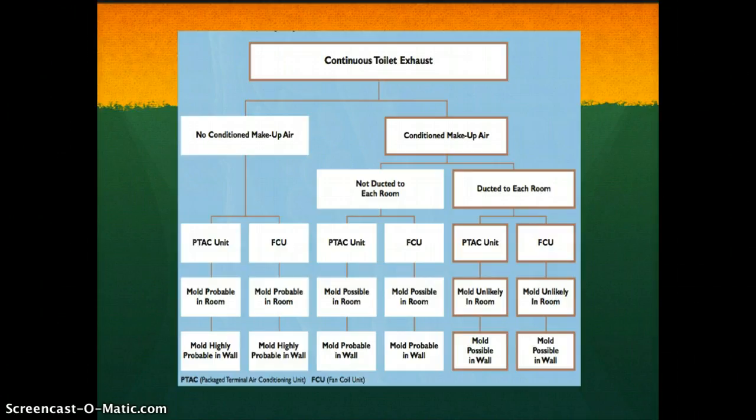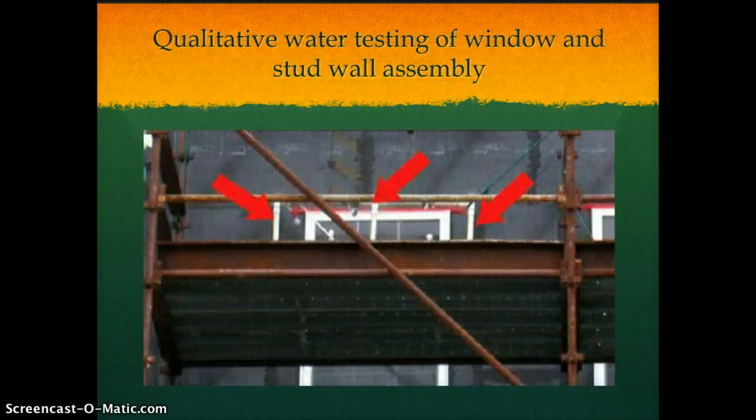A key to the review is to identify specific building components and systems with high potential for moisture problems and offer alternative solutions to the design team. An area often overlooked is the relationship of the building envelope and the heating, ventilation, air conditioning system due to the dynamic interaction between these two separate technology areas. The commissioning process needs to take a close look at the interrelationship of this area.